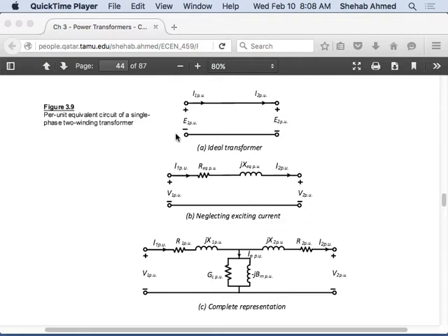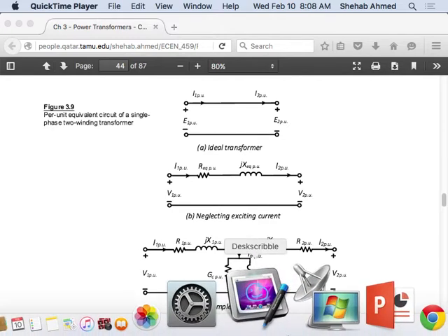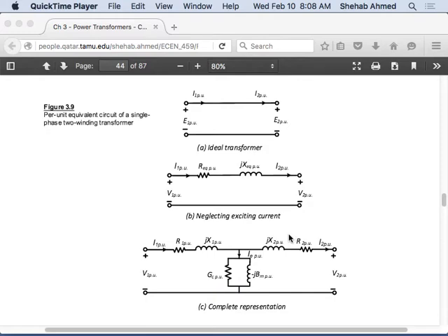And this is just in per unit, guys, right? If it's not per unit, the transformer stays there, right? If we did not convert or normalize everything using the per unit system, then the transformer stays there, which is a bit of a pain for us to analyze, right? And we don't even know how to do it for a star-delta transformer yet, right? So for a star-star or a delta-delta transformer, where the voltage in the primary and the voltage in secondary are in phase, it's easy. That's the case we studied. Today we will study the other case where we have a star-delta type transformer.